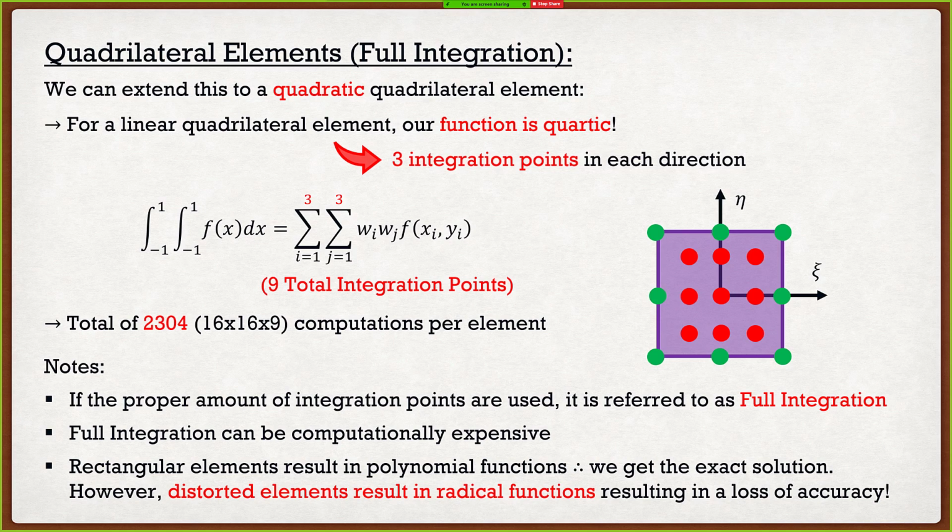So one of the things you guys might see, especially if you're running plasticity analysis in Abaqus, is you'll get warnings. The analysis won't stop, but it'll say this area of your beam or this area of your pipe, whatever, that those elements are becoming highly distorted. All that's doing is saying, hey, they're becoming distorted. Therefore, the accuracy is getting lost. So in that area, maybe take it with a grain of salt, because it's still able to run, but it knows that since those elements are getting really distorted, the accuracy is going down. So that's all it's doing.